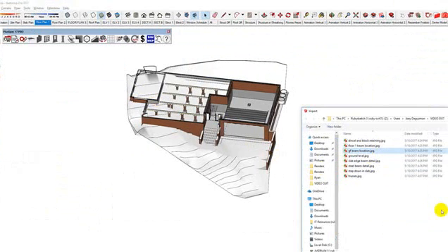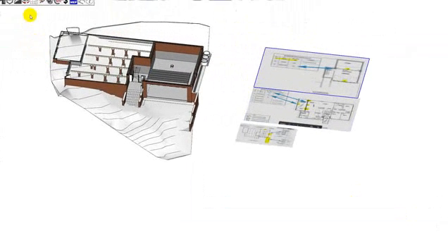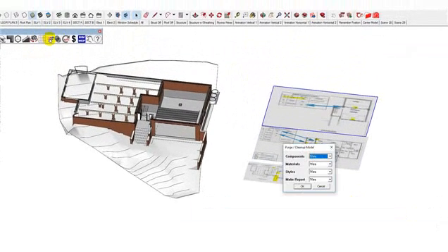next one. Notice that those file sizes are pretty small. If you do massive imports, you're going to get your model overloaded. And if your model ever does slow down, just make sure that you purge as you go. Took 180 materials out in one style. Everything you do makes it go faster.